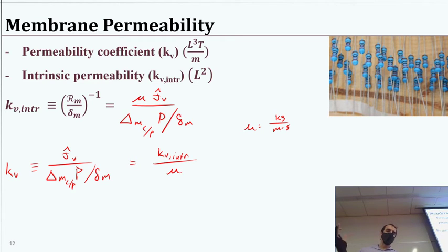But they were thinking maybe we can get a lot better permeability with the extra heat because the viscosity is lower, and make use of the ceramic membranes to derive a pretty good benefit: less pressure required to get the same treatment, given that we can handle the hotter temperature, and the temperature's there anyway. So that was a neat use case for adjusting the permeability and other aspects influenced by viscosity.